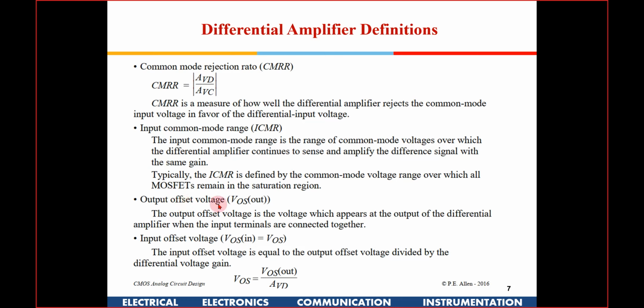And then you have an input offset voltage, okay, output offset voltage, for a differential amplifier. If both the inputs are of the same potential, if you are giving the same signal to both the inputs, or if the input terminals are connected together, 0 differential signal, then output differential voltage should be 0. But due to certain mismatches in the transistor parameters, due to wiring issues and all, in all practical amplifiers there will be some amount of output, a small output, it could be in the millivolt range. So that is known as V offset, okay.